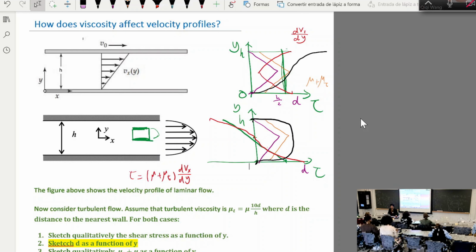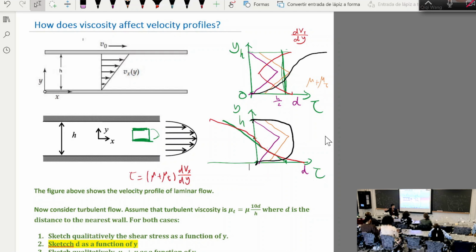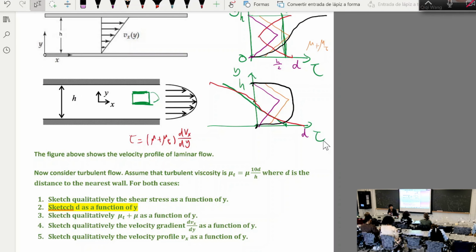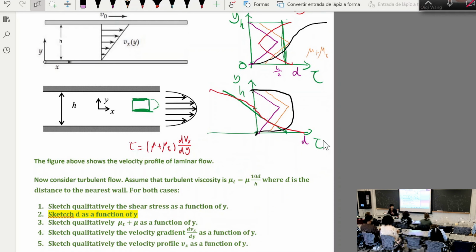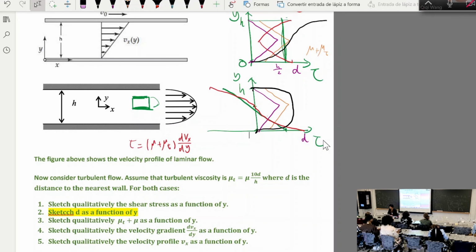I'm not going to talk about the reason in this class, but if you study advanced aerodynamics, strong rotation actually suppresses turbulence. So in regions where the flow is rotating a lot, for example, in the center of a vortex, turbulent viscosity is very low, and as a result, the center of the vortex is a region where you have a very high velocity gradient. Okay, that's basically near the wall, the center of the vortex is where you see velocity having large variation over small distance. And in the regions where there is a lot of mixing, large-scale turbulence, you expect the velocity profile to be shallow.